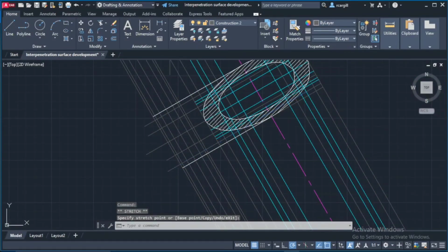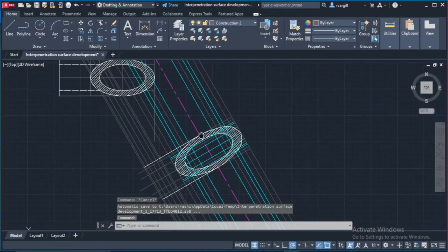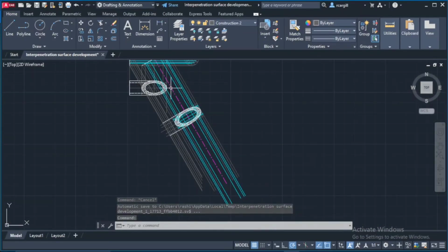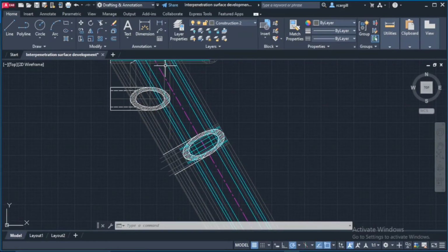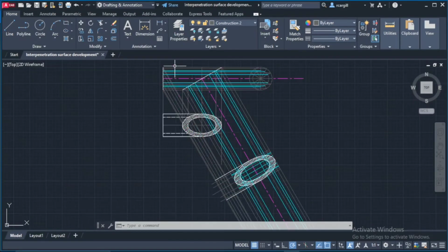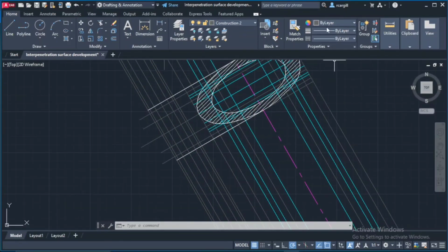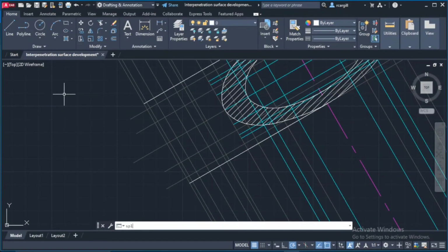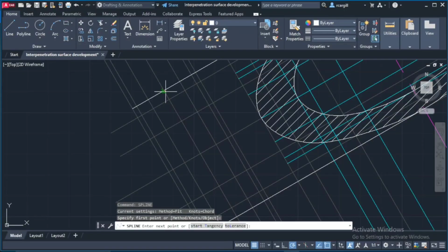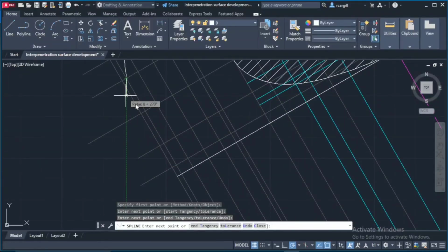And what do we get when we do that now? Okay, good. So this is what we get when we do that. When we do that, we end up getting an ellipse that looks like this. So let me go back to the zero layer here. So it's going to look like this. So type spline. So these two lines meet here. So this white line meets this center line right here, and we can make that our first point. Then these next two lines meet here, these two meet here, these two meet here, and these two meet here, these two meet right here, these meet here.